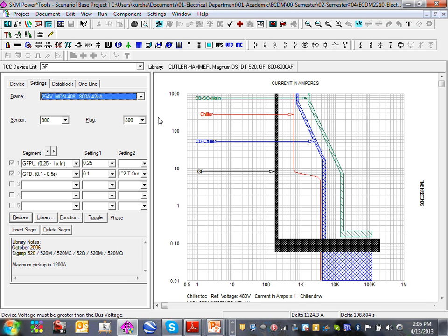This is looking at phase A, phase B, phase C, and the neutral, and saying how much current is going back through the ground. If you have a ground fault, more current will go through the ground. So it calculates the current in the phases and the current that goes back on the ground, and it trips if it's higher than the predetermined value. That's your ground fault, and it's typically required in hospitals. You're required to have two of these, at two levels and coordinated.